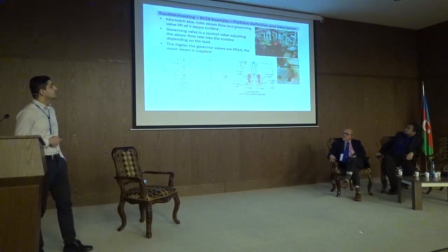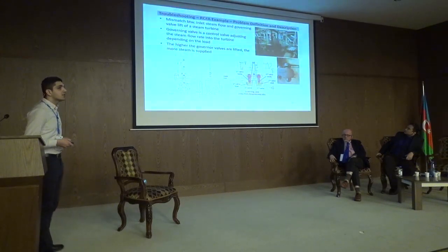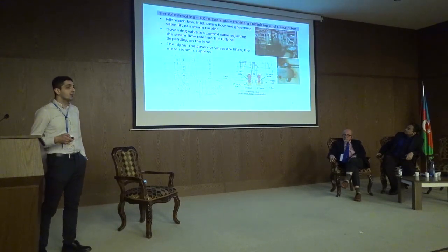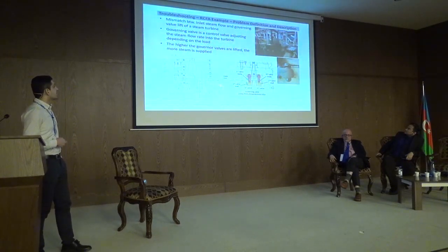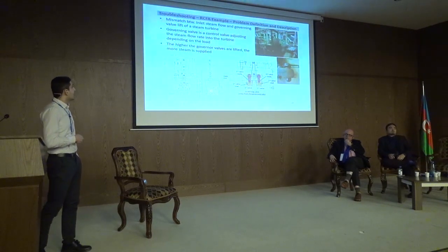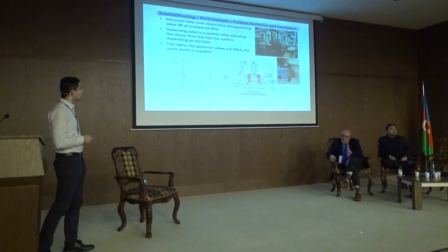It's a steam turbine of a natural gas compressor. Normally a steam turbine has an integrated governor valve. The governor valve is meant to adjust the flow rate into the steam turbine depending on the load on the steam turbine. The governor valve has an actuator and a lever. The actuator is meant to lift the valves, to control the valves here, as you can see. These are the valves. The higher the lever is lifted by the actuator, the more the valves are lifted, and the more steam goes into the steam turbine.